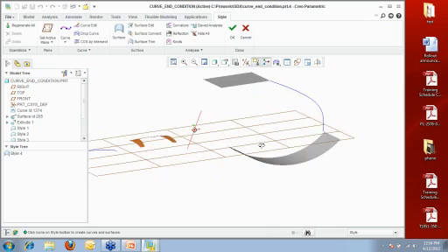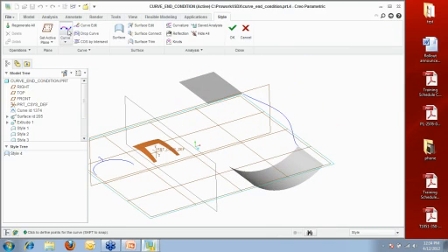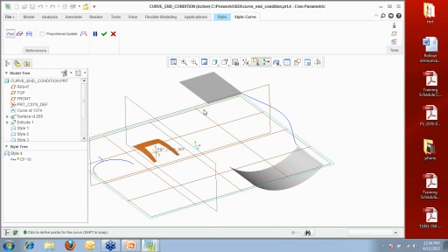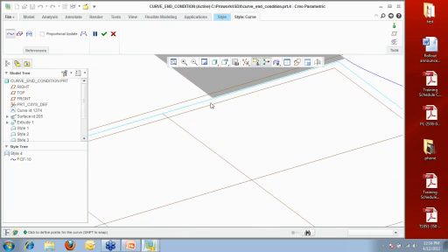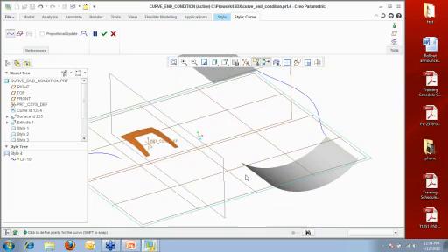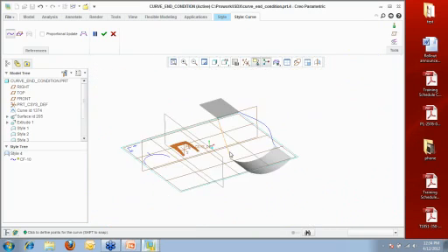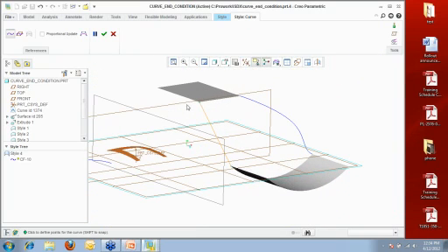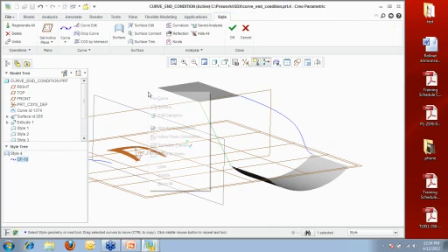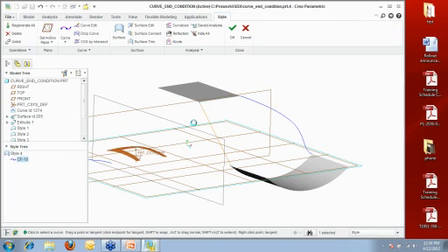So what I'm going to say here is curve, it's going to be a free curve, and what I'll do is say I want to attach it onto that endpoint, and attach it onto that endpoint right there. Again, here is my just straight line that I get. I'll come in and say edit definition, or it's just the edit of the curve.